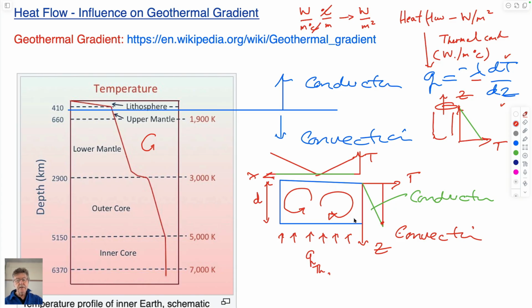As a result of that, any small packet of material will, as it's heated, expand. By definition, if it expands, it becomes slightly less dense because it's occupying a larger volume, and density is mass per unit volume. The volume's changed while the mass is the same, the density is reduced, and as a result of that, you'll get convection occurring. So I guess this is starting, it's not necessarily any particular direction. If this goes up, this will go up to the surface here.